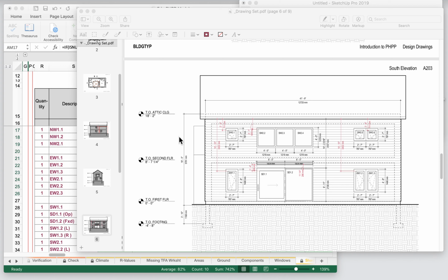So we've got a couple of things happening here. We've got some sort of typical windows on the left, south window 1-1 and south window 2-1. On the left-hand side there are sort of normal conditions. We've got some mulled windows on the far right, and then in the center we've got some oddball pieces there. We've got our sliding doors with some horizontal shading over them, and then we've got our triple mulled fixed units on the top, and then we've got our eave overhang to contend with as well. So quite a bit of moving parts on the south side here.